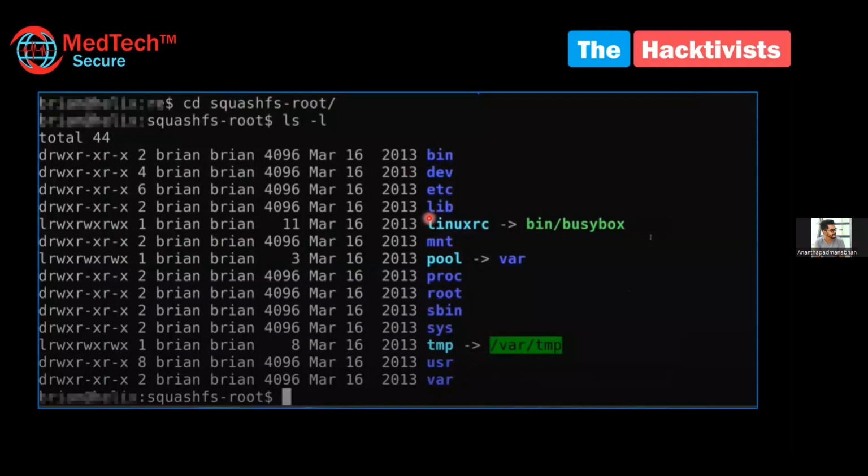So this is a kind of critical issue that we come across in hardware security. This is just firmware analysis. Suppose you're able to fetch out a firmware initially from the hardware perspective. If the device is properly secured, then the firmware extraction itself might be a difficult task. But if you're able to extract it, this is the methodology we follow for reverse engineering the particular firmware.